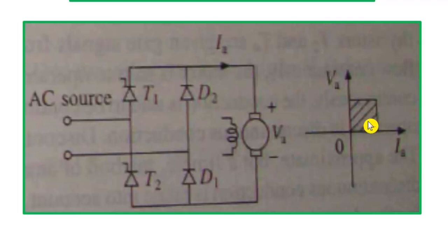The reason behind it is that when thyristor number 1 is off, then what will happen, as this is an inductor, so this inductor will change its polarity, and upper part will be negative and bottom is positive. Then in that case, this positive voltage will forward bias this diode D1 and diode D2 also. So the current will flow in this direction when switch number 1 is off.